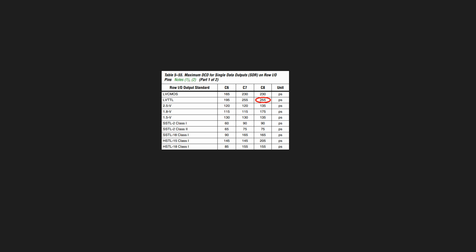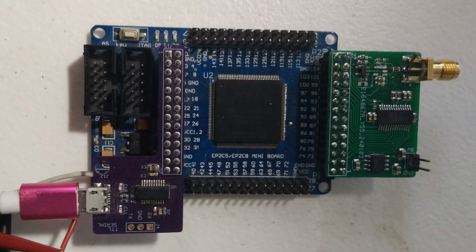A high-speed op-amp actually accentuates the spike. I tried pulse width modulating the least significant bit with a little filtering, and I was unhappy with the results. So I ended up going with the DAC.